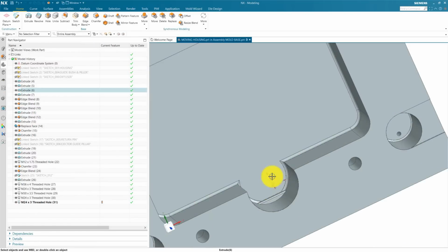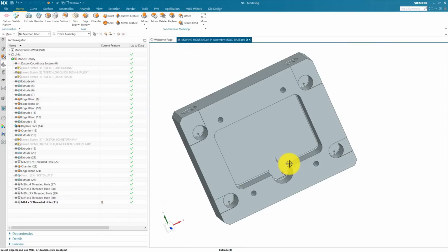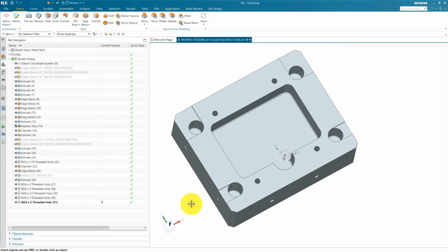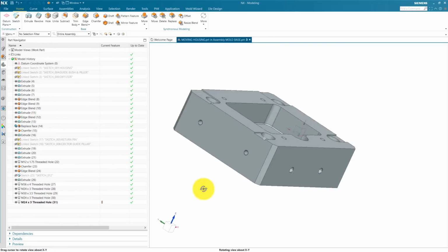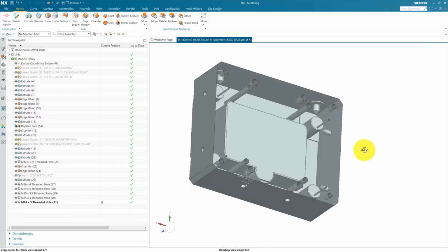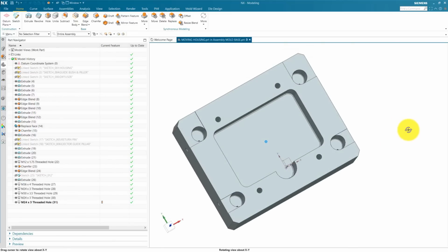We need to add a bolting hole for our diffuser, bolting hole for our insert, cooling hole for our insert, ejector pin hole for our insert. Maybe we need to add some slide, so we need to modify the area according to design. We need to add some chill vent. When we add a chill vent, we will add bolting for that, and when we design our diffuser or insert, we will add the bolting hole for diffuser and our insert.